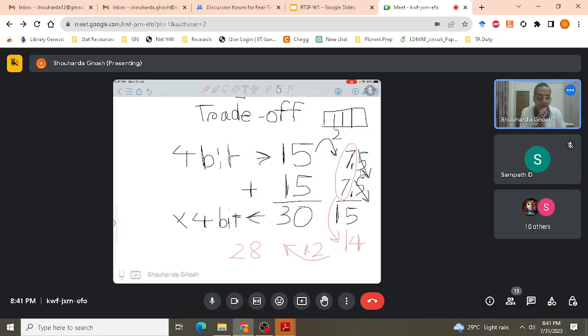That's something called a scaling factor, which we do not explicitly show or use in our hardware, but we keep it reserved with ourselves, with the programmers. The programmer or the hardware designer has to keep a ready reference for the scaling factors, so that whenever he gets internal variables in these registers, he will be able to obtain the original value by multiplying by the scaling factor. Now you see what happened.